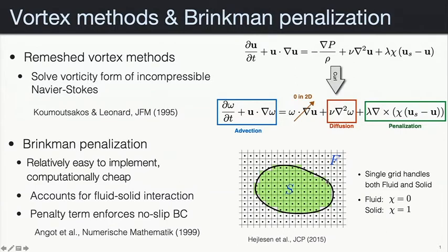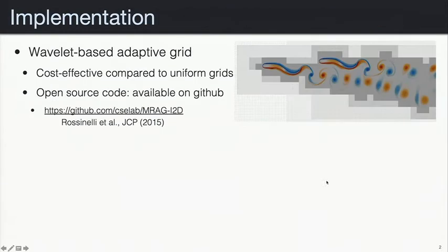Okay. So that's why we usually use this sort of adaptive grids in space and in time. Wherever there's a solid boundary, you make sure there's enough points that the smearing is almost invisible to the solver. And far away, you don't care. Okay? Does it make sense now?